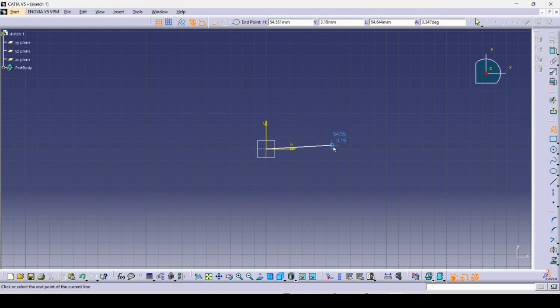You can see if we go horizontal and vertical, the line will be drawn in blue color, and when we get some angle, it will show in white color. We draw a line, and in profile we can continue drawing. So it's not like a single line and single profile. It will continue unless we press escape or double tap.